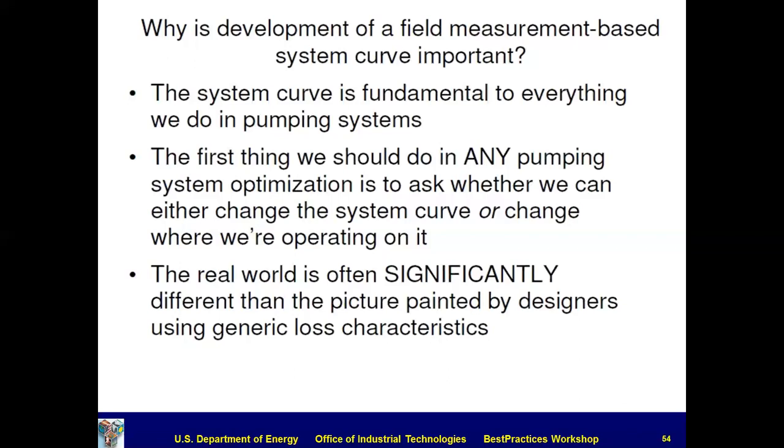And often we'll see that the real world is significantly different from the world that the designers see using their generic loss coefficient. So the actual system that's designed and built may be considerably different, in terms of flow and required pressure, from the one that the designer intended.